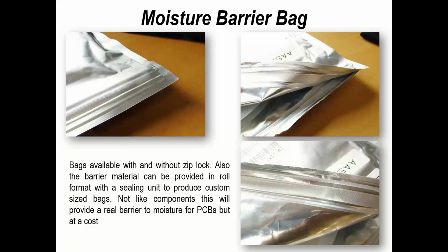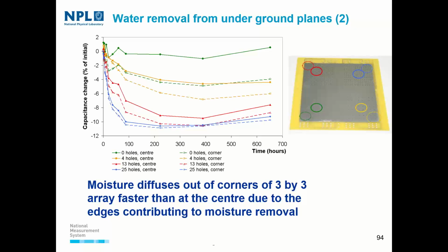If you're using nickel gold, you should absolutely expect a year's shelf life without any real problem whatsoever, and possibly longer. But when you're looking at tin finish, OSP, then again the solderability life is less, and also the impact of baking those boards again is less. So again, it's understanding those differences.